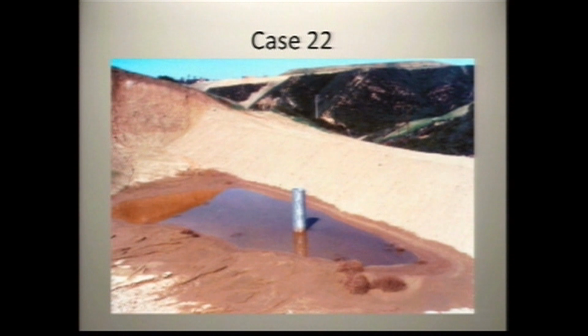So what's missing from here? A spillway. I heard somebody say it. Can't impound water without a spillway. If the primary outlet fails, the embankment's going to fail. Huge problem, huge liability. And you know, that's something obviously the site owner is going to be cited for and bear the brunt of it.